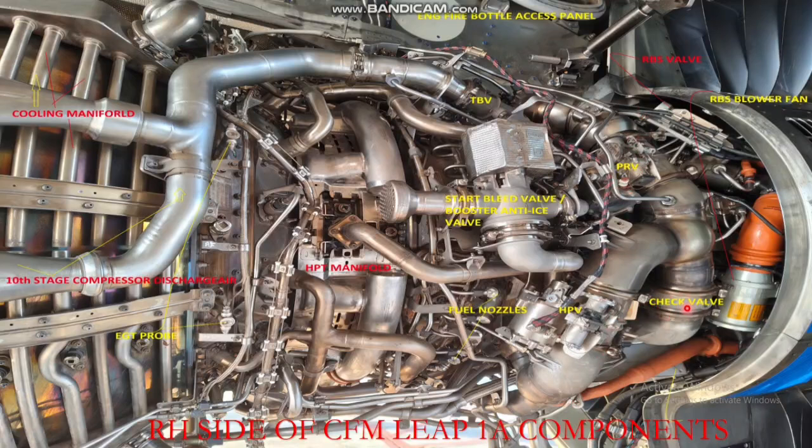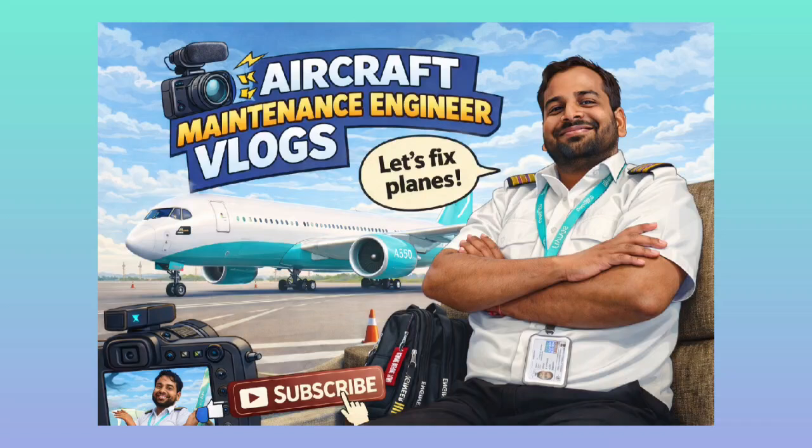Here you will find the check valve, and this is your reverse bleed, which is a new modification. For this also I have uploaded a separate video. And this is a reverse bleed blower fan and necessary duct. This is a reverse bleed valve, and another. And fuel nozzles also, you can see there are a lot of fuel nozzles. There are a total of 19 fuel nozzles in the core area. So this is the area where you can find the fan air valve inspection rod. Sometimes the rod will break, and you will find a bleed fault, so you can check that rod condition from that particular panel.